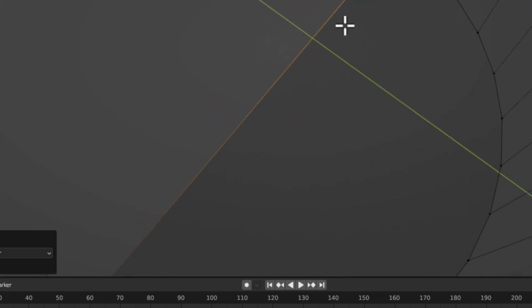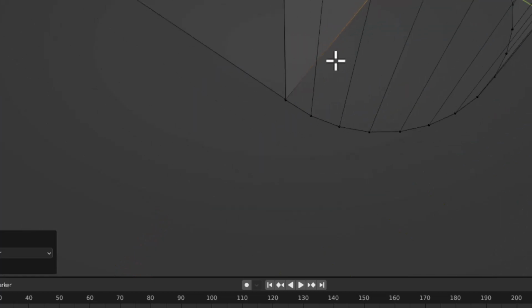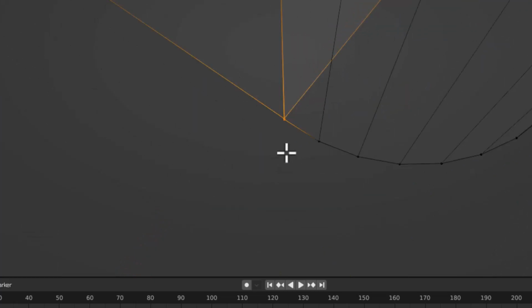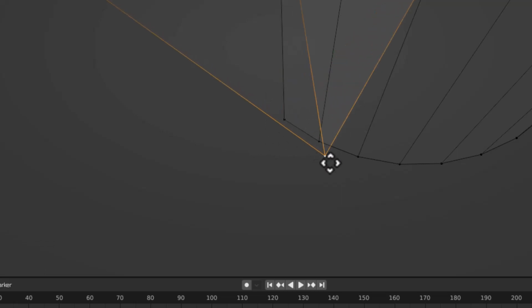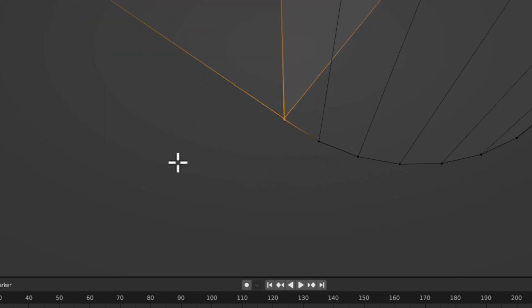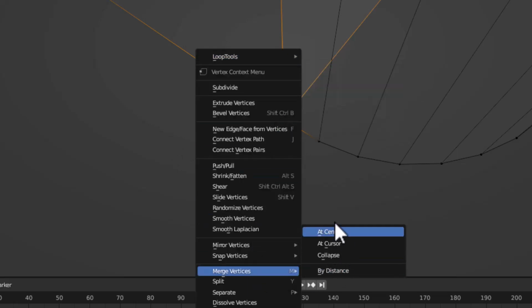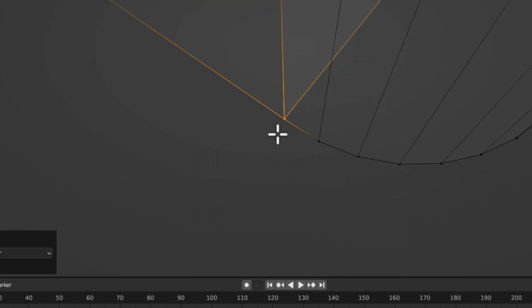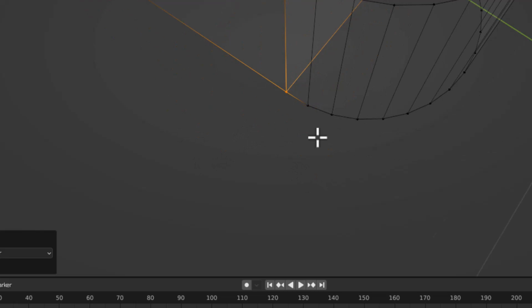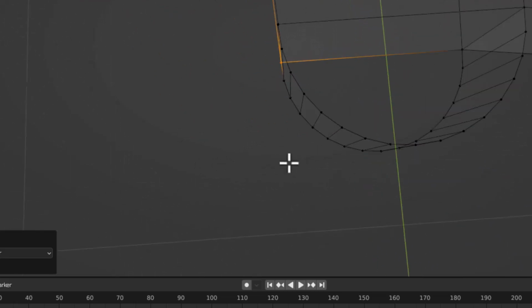I will right click. So, like this I can do it at all the 4 corners here. Right now if I select this vertex and move it, you can see it is moving separately. Okay. I will right click it. I will drag a box here and select both these vertices. I will now right click, choose merge vertices at center, and now you can see this is combined as one single object. So, like this we can merge these vertices.